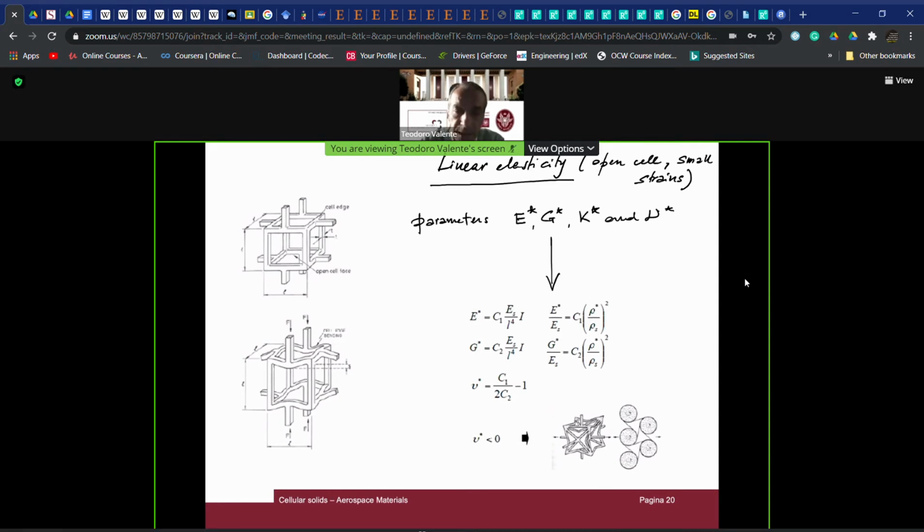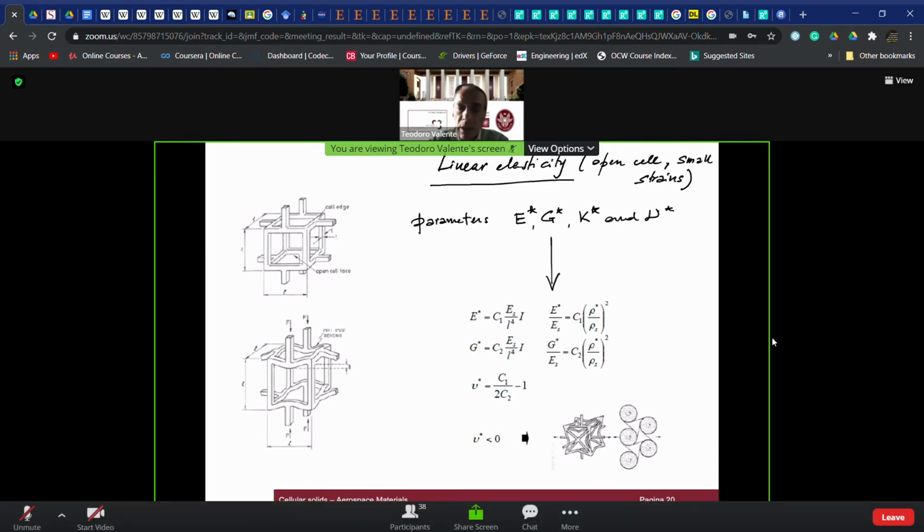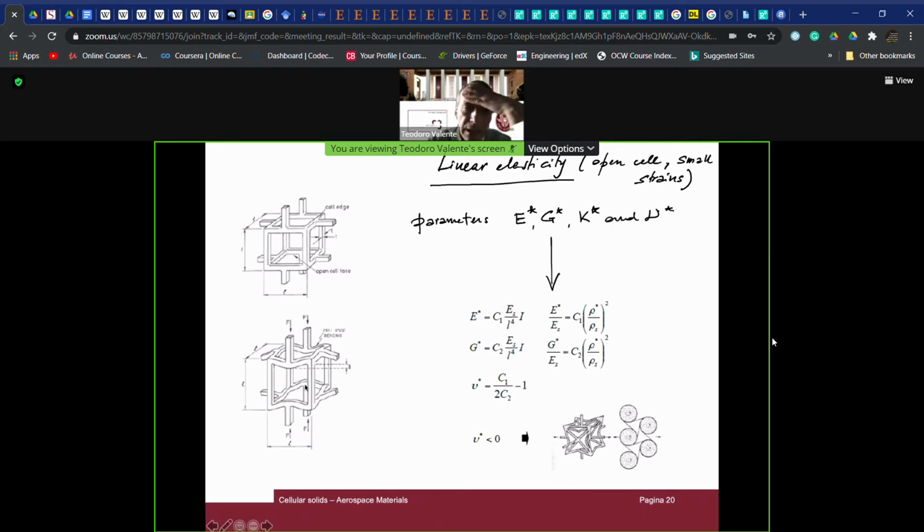But I repeat, this effect is not related to the fact that the base material has changed its fundamental properties or answer, that is, each time we put the material in a tensile mode, it has an elongation and vice versa for compression, but it is just a result of internal deformation of the beams, which are the basic elements of the cells of the cellular solid.